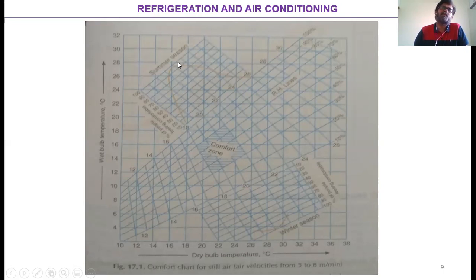And along this inverted U-shaped curve, and this one would be the U-shaped curve, it will be seen that at the peak of this particular curve the value is nearly 97-98%. It means that at this value, 98% of the occupants sitting in that air conditioned space in the summer season will feel comfortable, provided the temperature is somewhere around 21.5 or 21.6 degrees Celsius. So almost 98% of the occupants will feel comfortable when the effective temperature is of the order of 21 degrees Celsius. This is also a line of constant effective temperature of 21 degrees Celsius. But it will be seen that somewhere around 90% of the people will feel comfortable when it is the winter season.